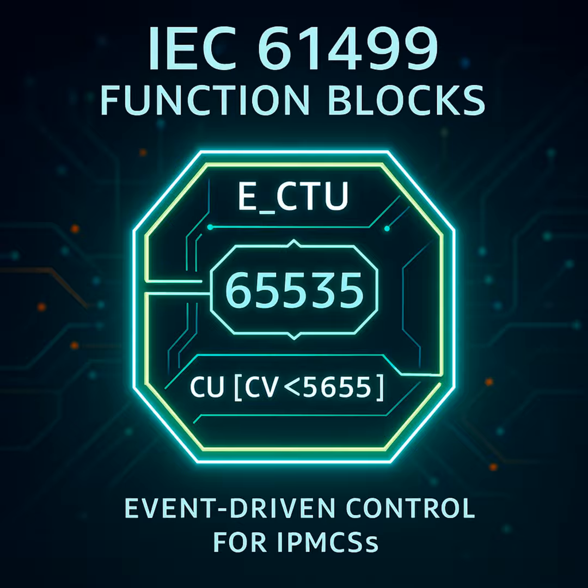For CU, there's CUO, count-up output. Ah, signals completion. Exactly. It fires after the counting operation is finished and the internal value is updated. Yeah. And similarly, there's RO, the reset output, which signals that the reset is done. So those outputs are crucial for chaining logic together reliably. You wait for the CUO or RO before moving to the next step in your sequence. Precisely. The action isn't complete until that output event fires.